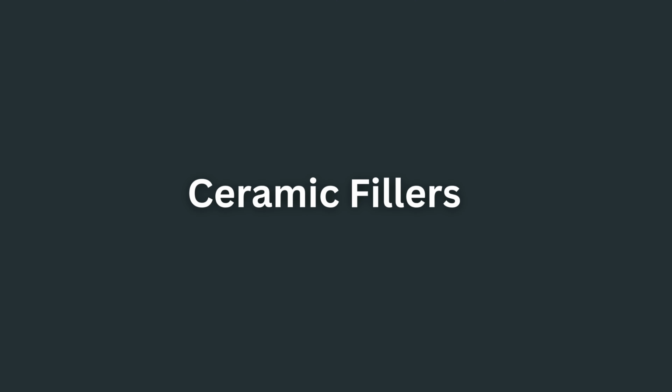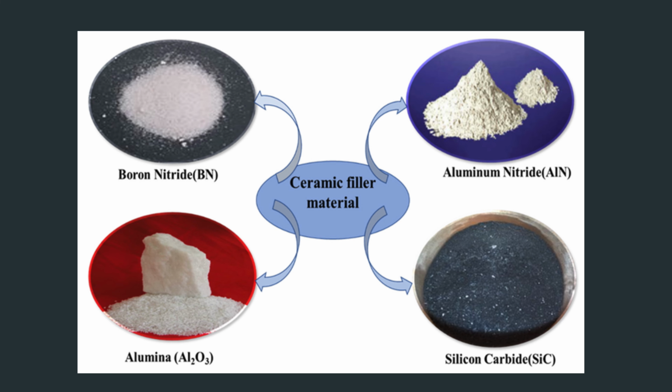Ceramic fillers. Ceramic fillers are particularly important for thermally conductive adhesives used in electronic devices because they provide high thermal conductivity while maintaining electrical insulation. This property prevents electrical short circuits while enabling efficient heat dissipation. Common ceramic fillers include aluminium oxide, aluminium nitride, AlN, boron nitride, BN, and silicon carbide, SiC.